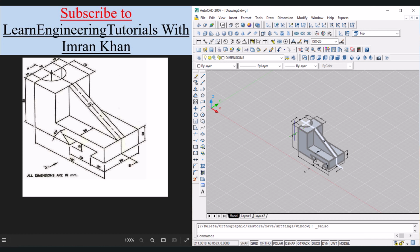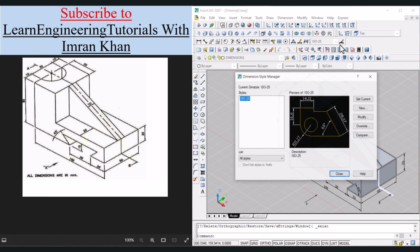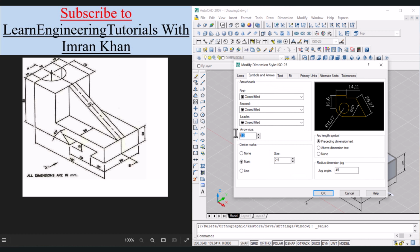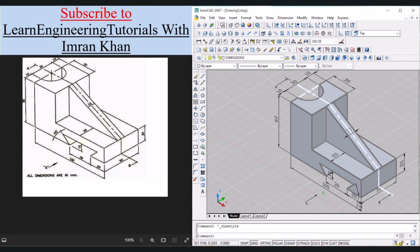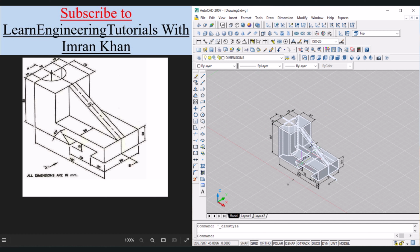Now everything looks complete. If you want to change the dimension style, click on this dimension style icon, click on modify, click on text, let the size be 4, click on offset from dim line, let it be 2, click on symbol and arrows, let the arrow size be 3, click on primary units, let the precision be 0.0, click on OK, click on close. We can see that the size of the dimensions have been increased. Now the diagram looks complete. There is just one or two things to do.